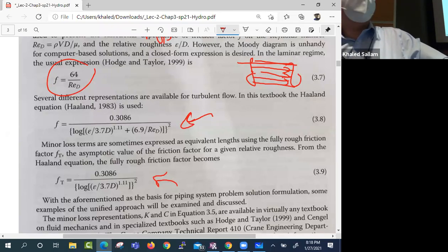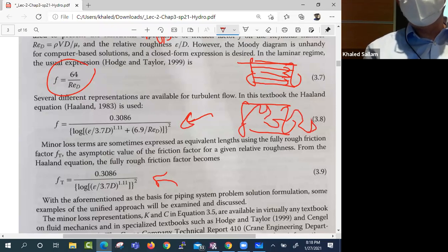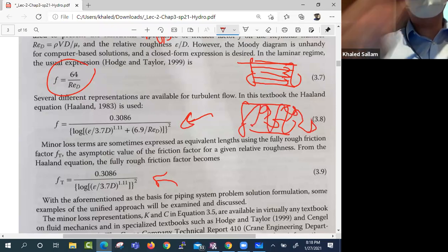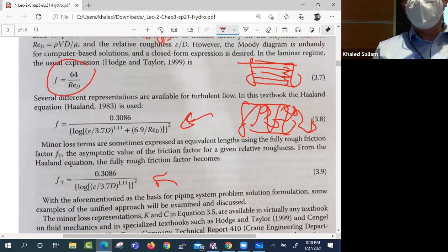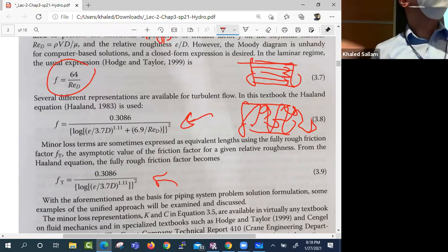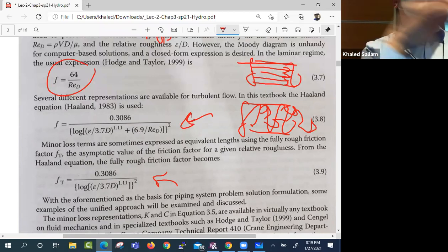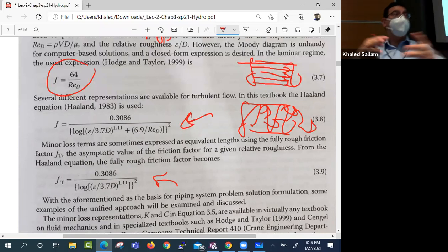But if there is turbulent flow, which looks like what? This is the turbulent flow. The flow goes from right to left, yes, but in what direction? Bum, bum, bum, bum. This is actually very good for mixing. People in industry, when they have a mixing line where you add a bunch of chemicals together, they love turbulence.